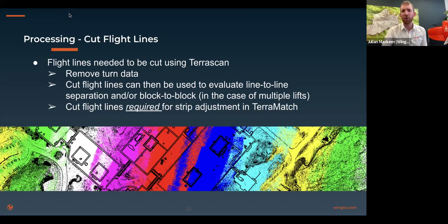Yeah, I wanted to take several questions that are coming in regarding the payload itself. The payload weighs about 1 kilogram, and it's the combination of the sensor, the IMU, and the GNSS. As Ravi was mentioning, we need a base station in every flight in order to put all of this together. This is different from photogrammetry, where you could use PPK or not, and then use GCPs. Here, you need to use the base station in every flight. The reason for it being heavy is that it has all of this very expensive and very accurate equipment that makes the LiDAR payload.